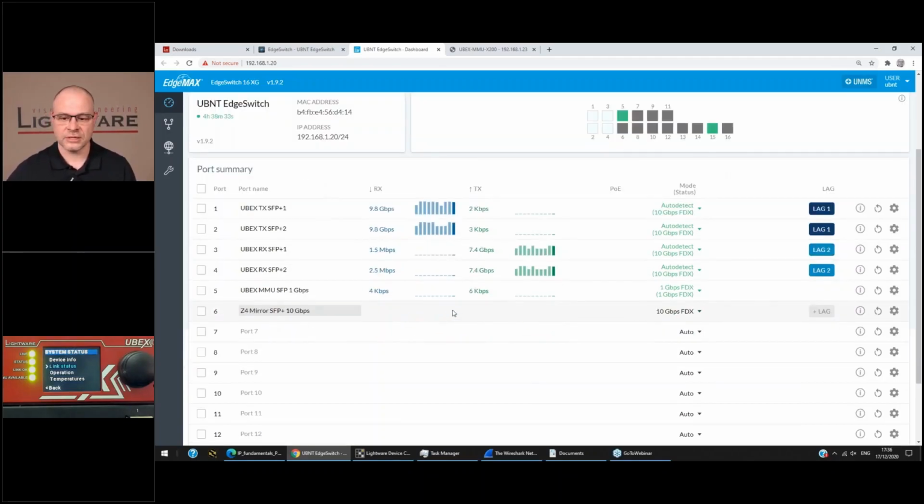And this is one of the things that is important for us to remember. If we are setting up a device like this, then right now we have 17.6 gigabits per second coming out of the transmitter, and about the same amount of information going into the receiver. Down here, because this is a configuration interface, it's not receiving, and it's not supposed to receive any more than a few kilobits per second. This is what we need to make sure we understand.